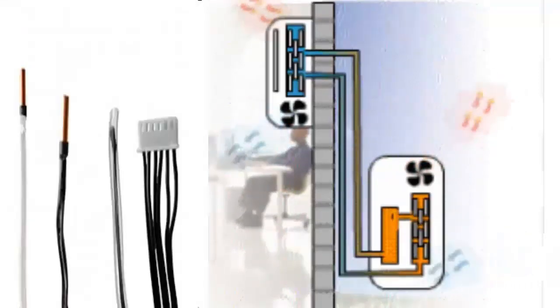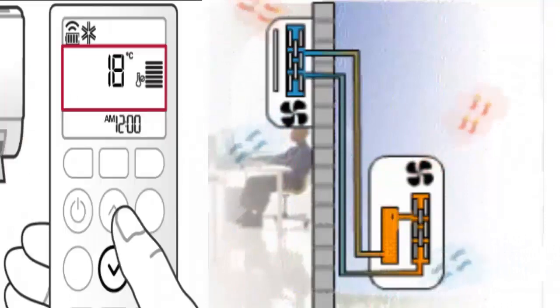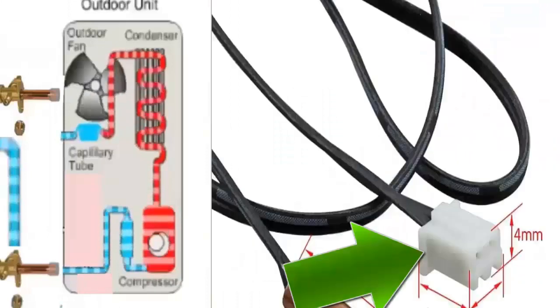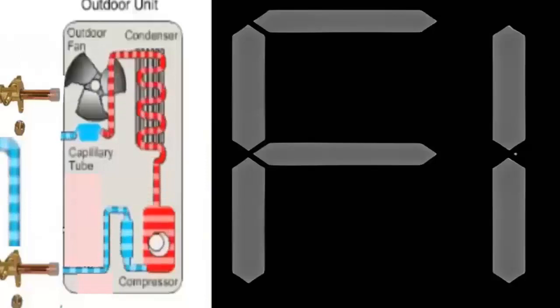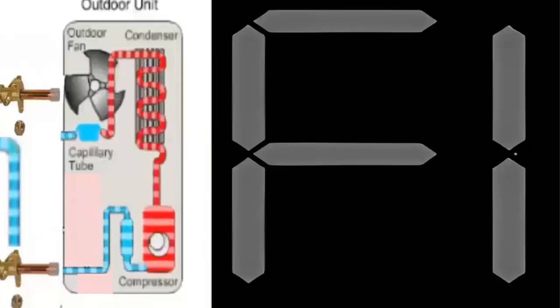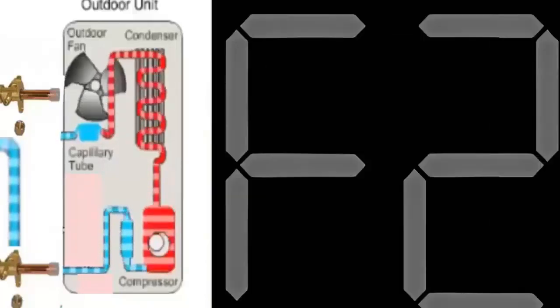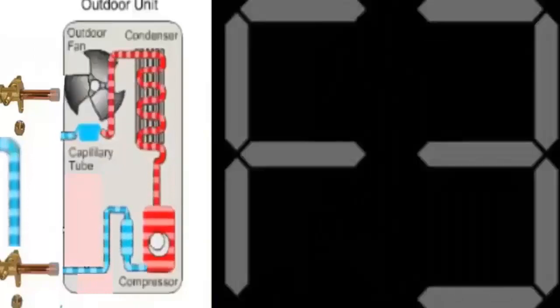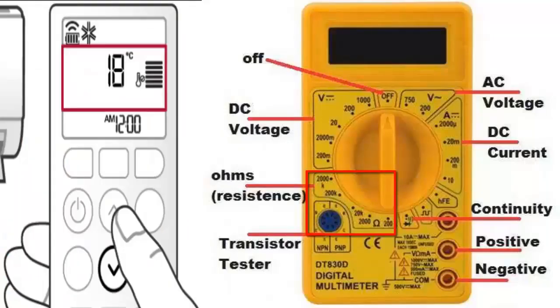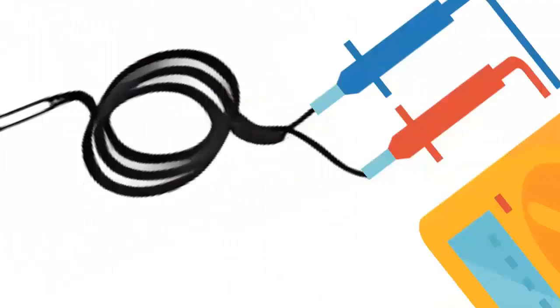4. Eliminate moisture on the sensor, and clean it with a dry cloth. 5. Additionally, check for possible false contacts of the sensor with the external electronic board, as well as the condition of the wiring. 6. If everything looks good visually, disconnect the sensor from the electronic board. Use a multimeter on the kilo-ohm scale to measure the electrical resistance of the sensor.